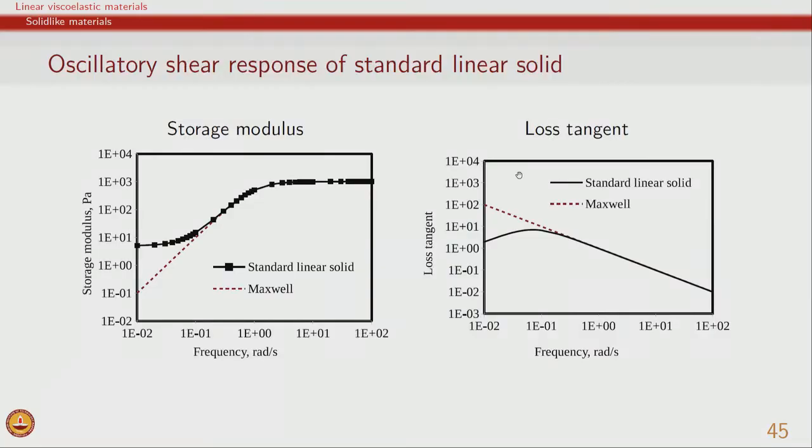never be observed. But if, on the other hand, we are using the material as a structural material, then we have to make sure that it is used much lower than the glass transition, because if a higher temperature is seen, a soft, flexible response with modulus 3 orders of magnitude lower will be observed, which will not be suitable for structural applications. Therefore, glass transition is important for many of the mechanical applications of glassy and rubbery systems.